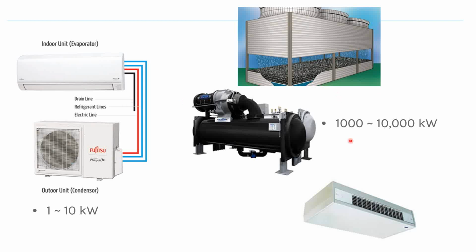So in this system, if we only look at this indoor environment, let's take summer as an example. You will have the air exchanging heat with some pipes inside this coil. So in that way, it's actually a heat exchanger. Your heat within this room is taken away by the cold water pipes inside this one. The cold water pipes are connected to this chiller, and this chiller contains the refrigerants.